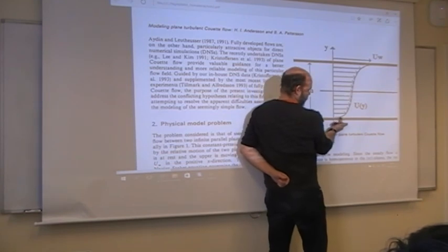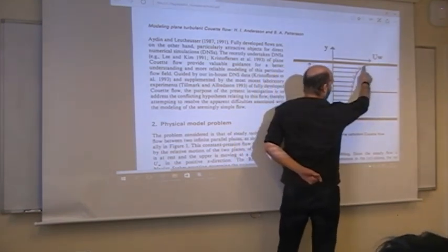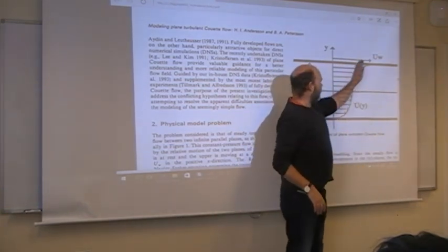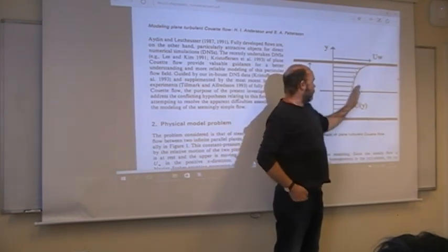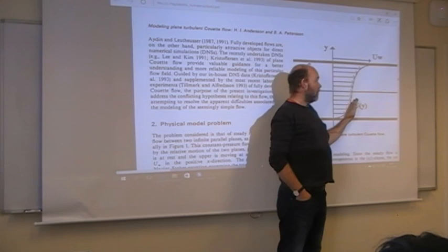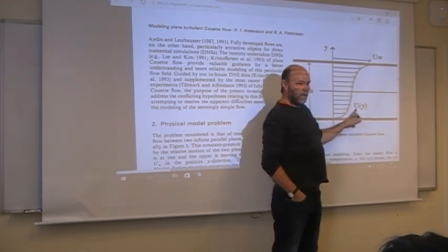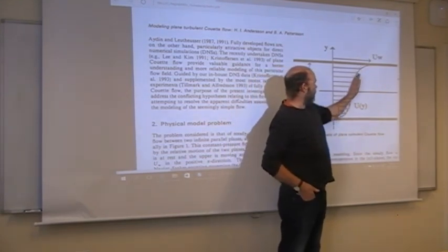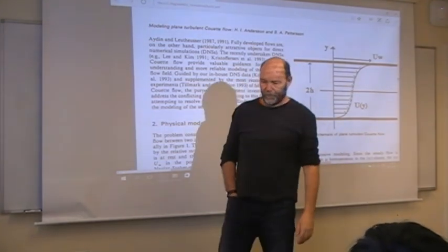This shoulder will become closer and closer to the walls. And also this one will be very, very steep. But then you will have a larger and larger center region where the velocity gradient is constant. So having a constant du/dy sort of simplifies your equations a lot, and then you can do a lot of investigation here in this center region. So that one is sort of interesting.